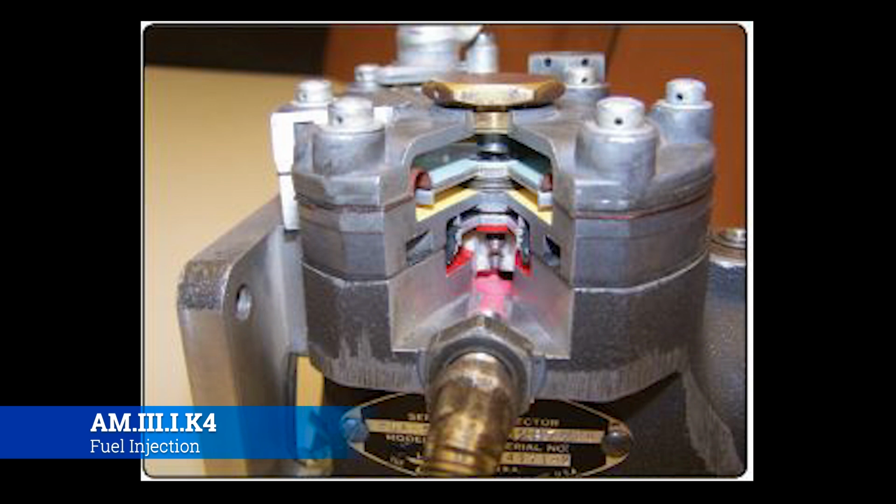As a result, the diaphragm moves to the left, opening the ball valve, and contributing to this force is the impact pressure that is picked up by the impact tubes. So essentially, this is the mechanical sensing device that says, hey, look, the airflow is increasing, so therefore we're going to add a little bit more fuel pressure, or the airflow is decreasing, so we're going to pull it back to maintain that 1-to-1 ratio. So if you have a mixture problem with a fuel injection aircraft, it's very likely that this is going to be where the problem is at.